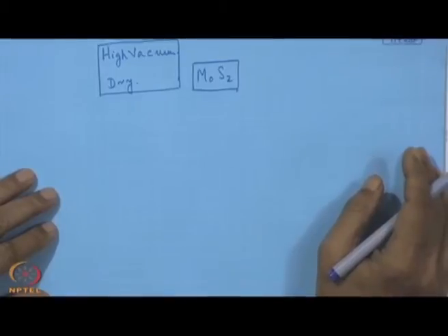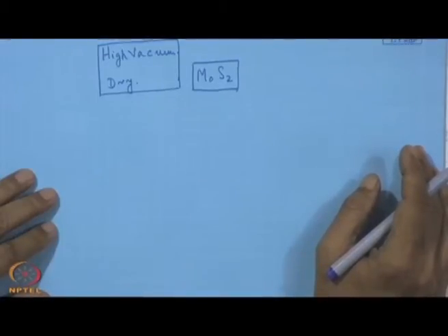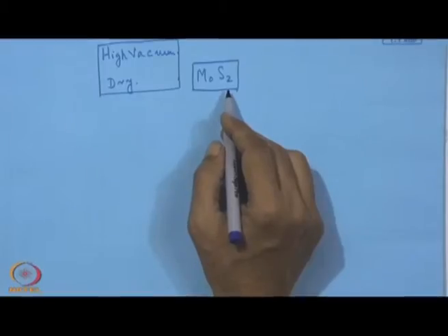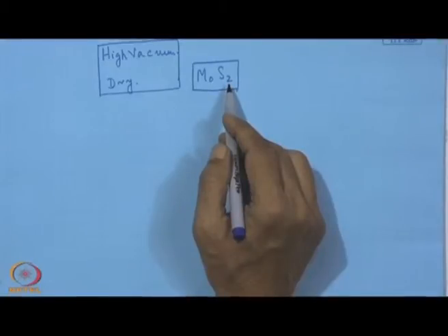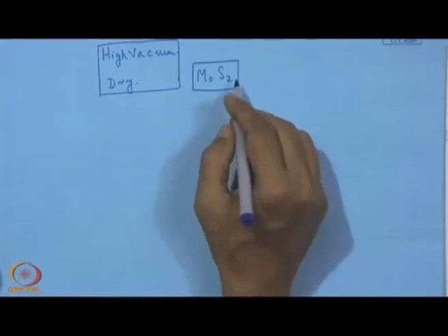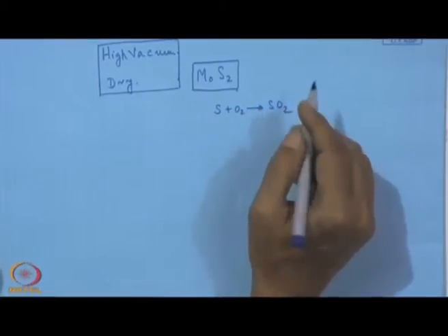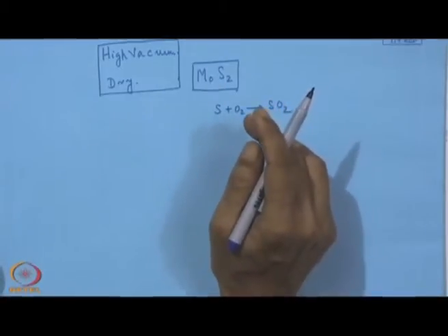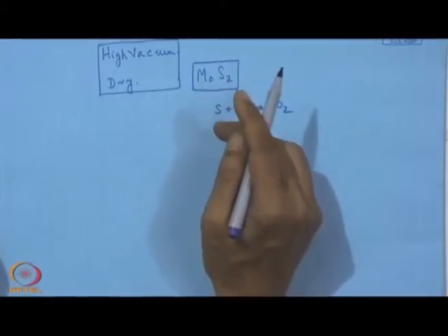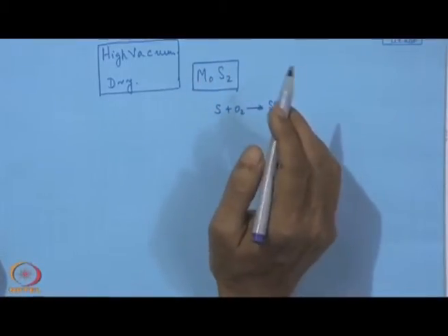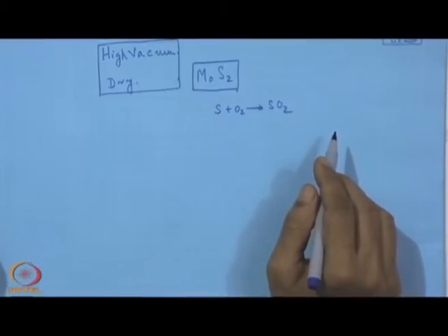But when it comes to practical use, normal use and field use, where we cannot maintain this low value of humidity and it is a normal atmosphere, in that case this MoS2 can show its weakness. It will simply absorb moisture, and then oxygen will be active, and this sulphur will be attacked. S and O2 will lead to sulphur oxide. So, oxygen will convert this sulphur into sulphur oxide, or it can go inside and also make molybdenum oxide. There are a lot of investigations and documentation on this particular subject. Whatever may be the case, ultimately it is the total failure of the coating.